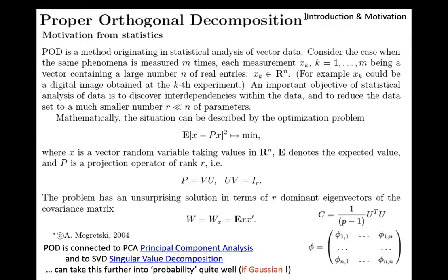So if you want to simplify to dynamics, you might be producing this response for some, like you have a cantilever beam, and you apply force at the end, and the response that you compute will be dominated by the higher order modes. But then if you take this truncated basis for some kind of loading which wakes up higher order modes, then your response will be not very good, or the other way around if you compute it.